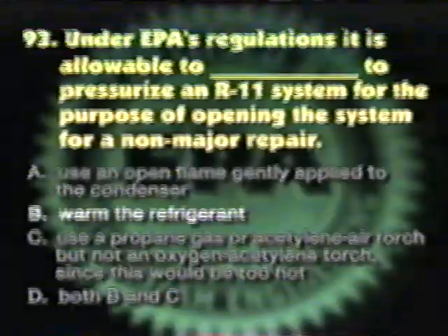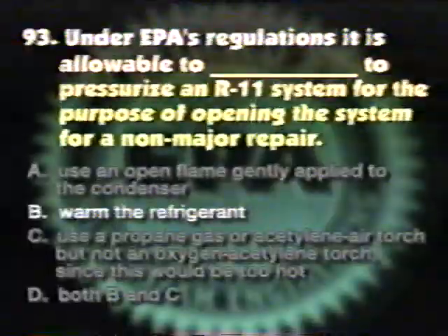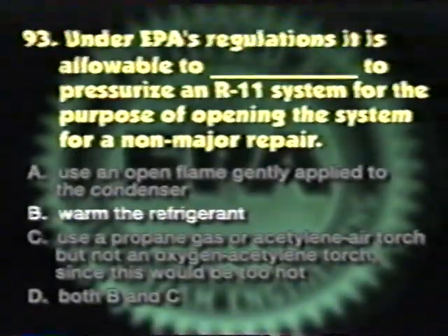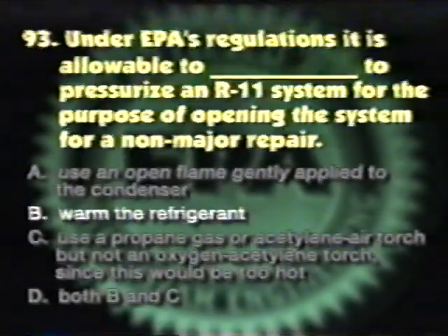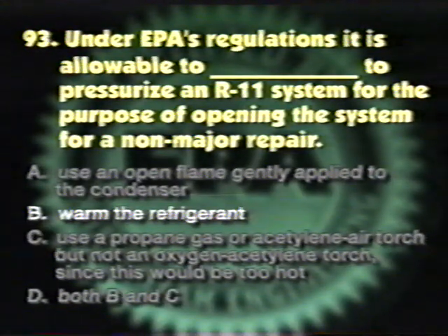The answer is B. The EPA recommends warming refrigerant with hot water as a method to pressurize an R11 or R123 system for the purpose of opening the system for a non-major repair.